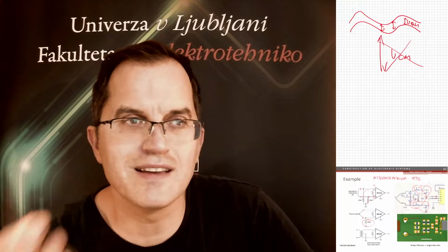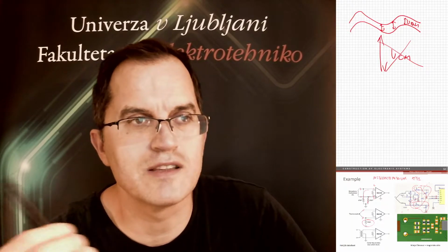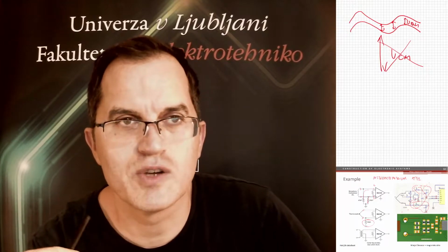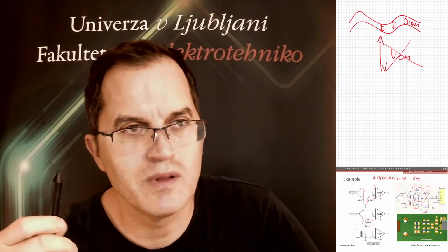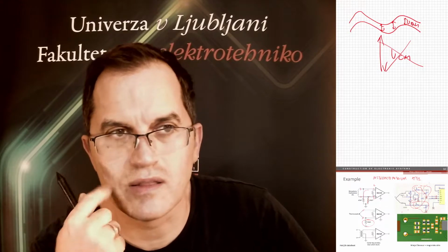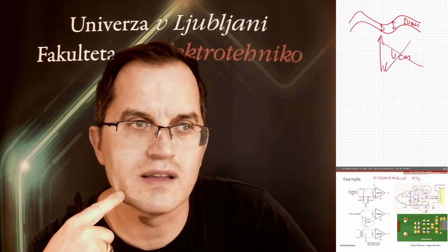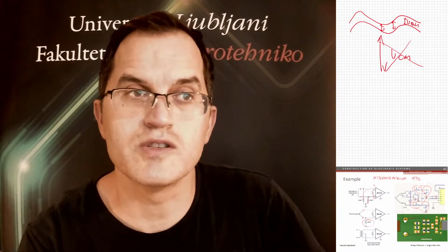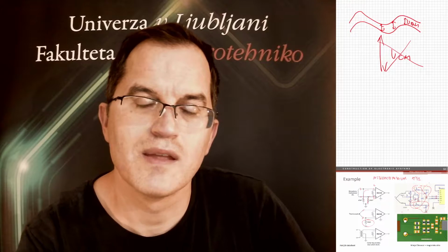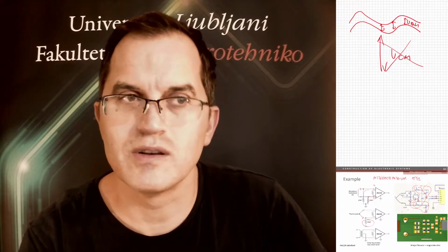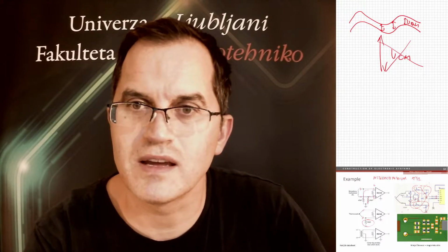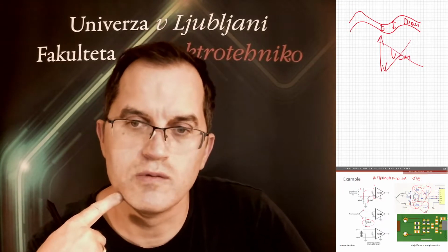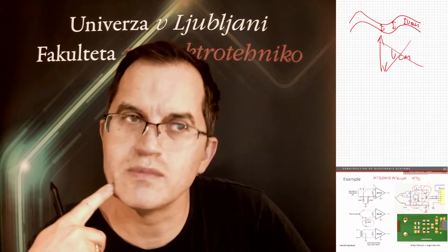If you have single-ended inputs, which are all defined toward ground, then you cannot do that. So if you want to be really immune from external noise sources, you might go for a differential design. And this is also a choice you make at the beginning. Later on, if you find problems with that, it's too late, because you have to go back to the drawing board, which might not be possible anymore.